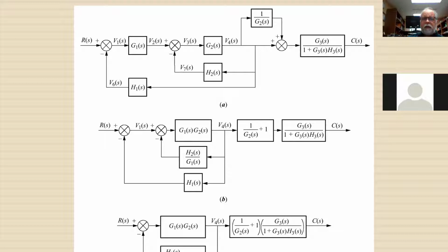When you do that, let's say you had a resistive network with 4 different voltages in it. When a voltage is between 2 resistors and you combine those 2 resistors, you lose that voltage. So here you see that we've lost V2 and V3. Can't get those from this drawing because they're internal now.